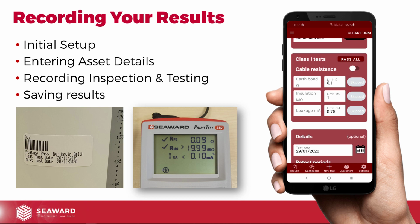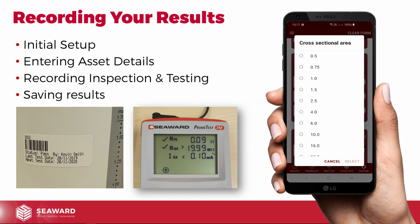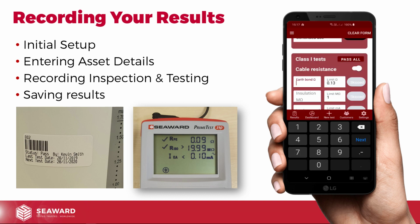So in this case, all I need to do is enter those results in. For cable resistance, I can use the resistance calculator on here. The cable size for the kettle was 0.75 and the length of it was 1 meter. So we can apply those limits and it puts those in.